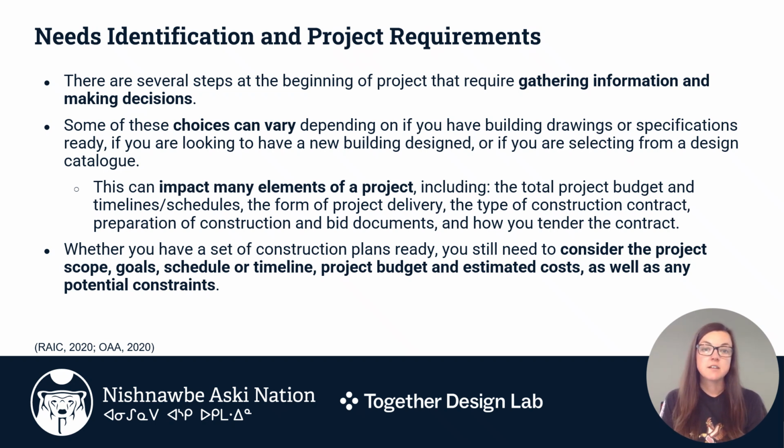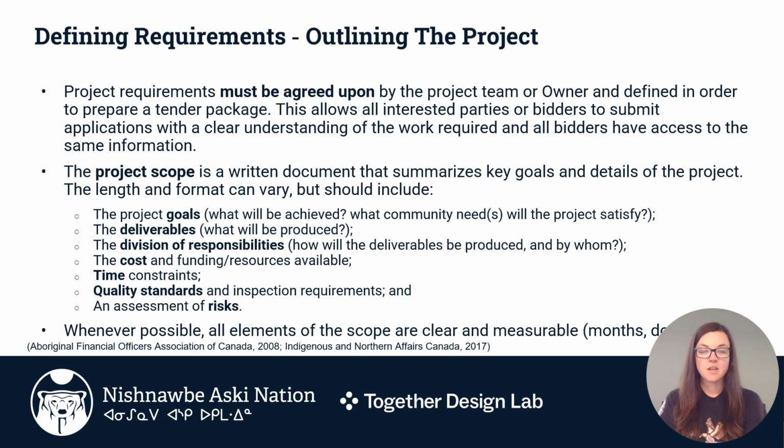Whether you have a set of construction plans ready, you still need to consider the project scope, goals, schedule or timeline, project budget, and estimated cost, as well as any potential constraints. Project requirements must be agreed upon by the project team or the project owner and defined in order to prepare a tender package. This allows all interested parties or bidders to submit applications with a clear understanding of the work required, and all bidders have access to the same information.